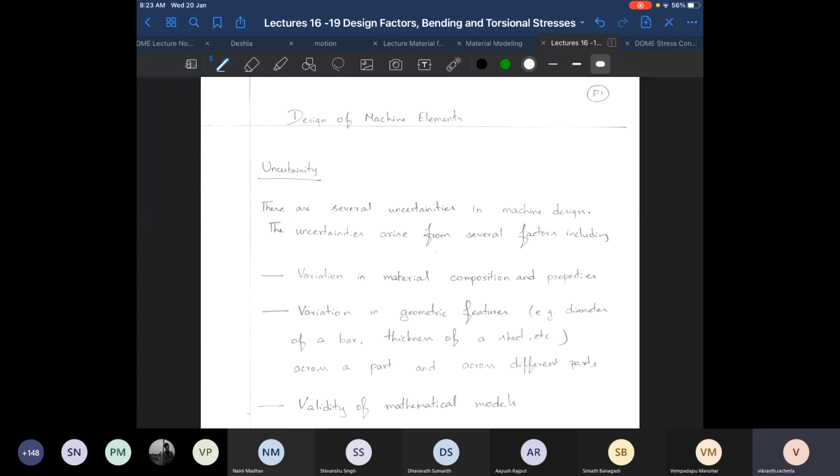You can either take the invariants to be the three principal stresses, or you can work with invariants such as trace, determinant, trace of stress square. Amongst the most popular stress invariants are hydrostatic stress, von Mises stress, and the three principal stresses. And once you know the three principal stresses, I had also said that you can go ahead and estimate the maximum shear stress acting on any plane within the material.